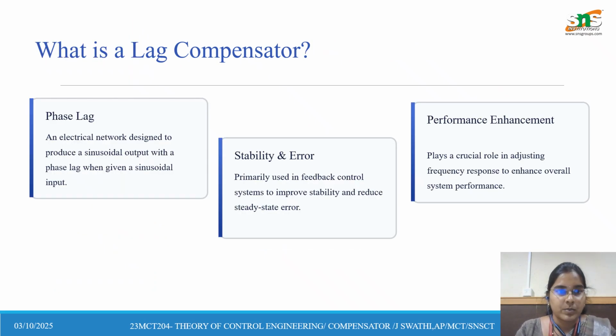So what is this lag compensator? It is an electrical circuit designed to produce a sinusoidal output with a phase lag. It reduces the steady state error, and it enhances stability by decreasing the overshoot and increasing the phase margin. By acting as a low pass filter, it smooths out high frequency noise while maintaining a consistent steady state output.